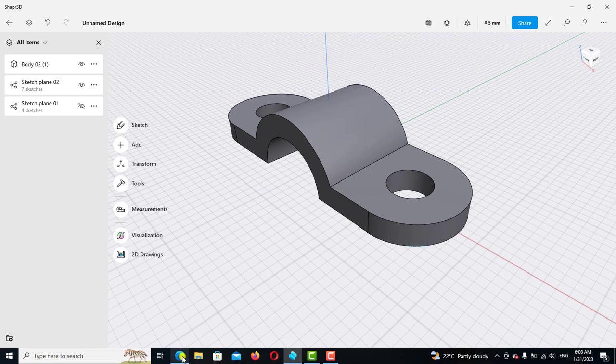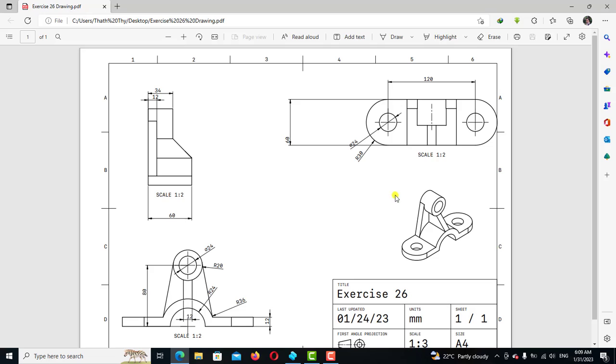And then we have to create another part of the object. We have to create the top part. It looks like a cylinder. It was created by the circle. The inner circle to make the hole is 24mm diameter, and the outside is 20mm radius, and the distance from the bottom of the base to the center point of the circle or the cylinder is 18mm. The thickness of the cylinder is 34mm. After creating the top part, we have to create the wall thickness. It has a thickness of 12mm.